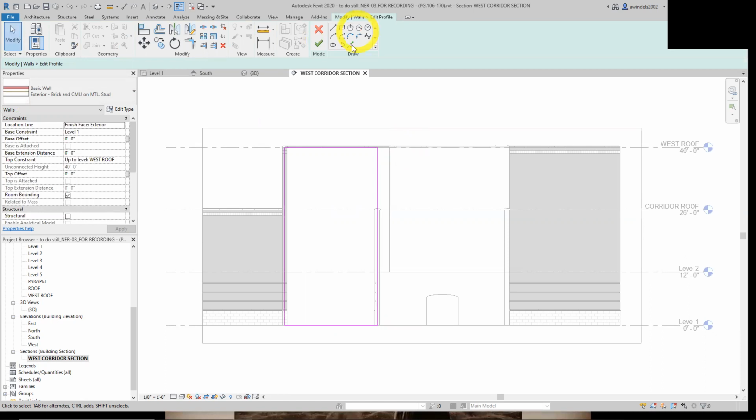Got all that. We're going to say pick lines button, offset of 2. Always check your options. And your status bar down here, it says select an outline or edge. It's trying to tell us what it's trying to do. So those are options and status bar, your friends all the time. Magenta wall is going, edit profile, we're ready to start drawing.